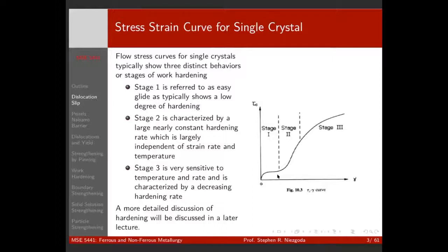Solid solution. Solute atoms, other atoms to get in the way, which means basically strain. So that's it. Those are the only four things, the only four knobs we have to turn. We can put in elements to do solid solution strengthening. We can put in elements to cause secondary phases. We can change the grain structure, or we can beat the hell out of it. That's all of strengthening in a nutshell.